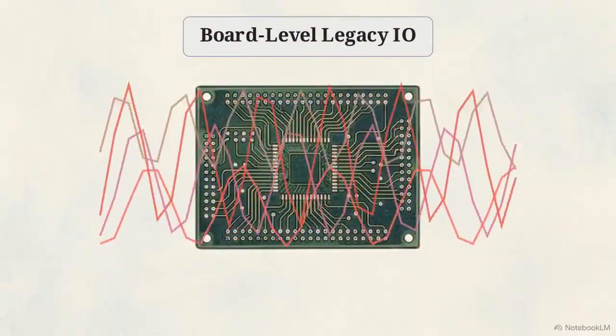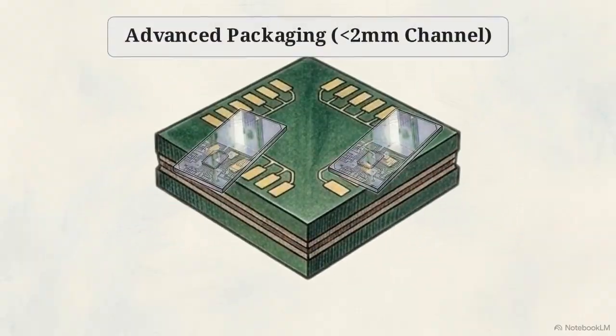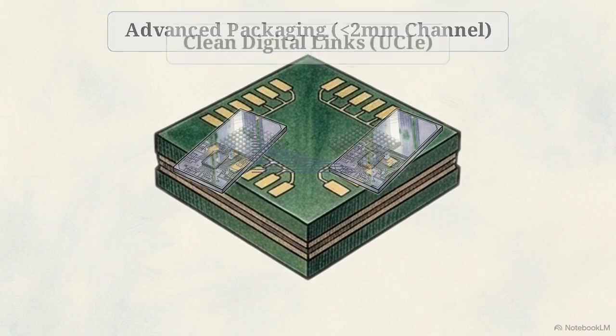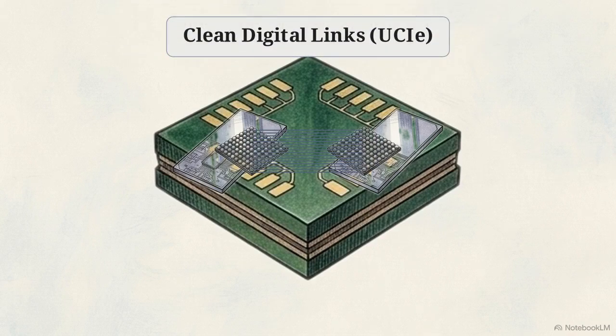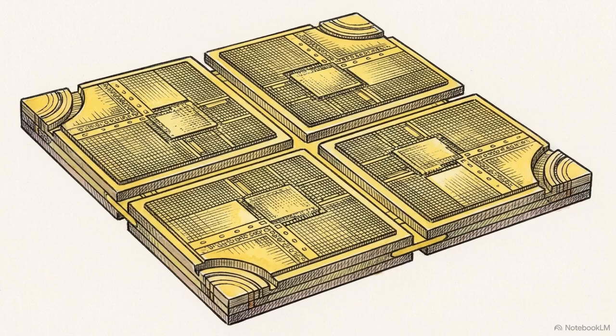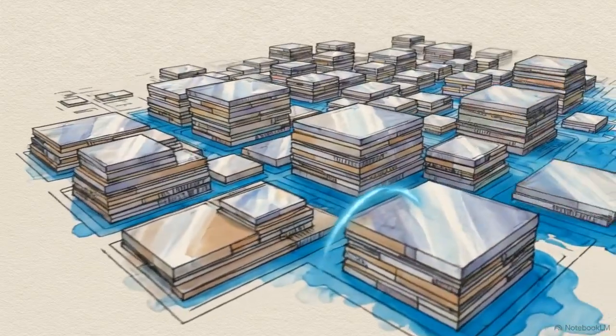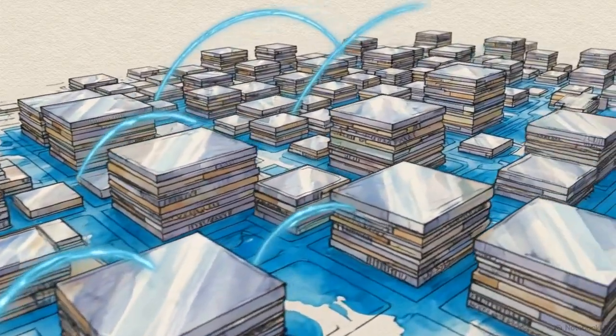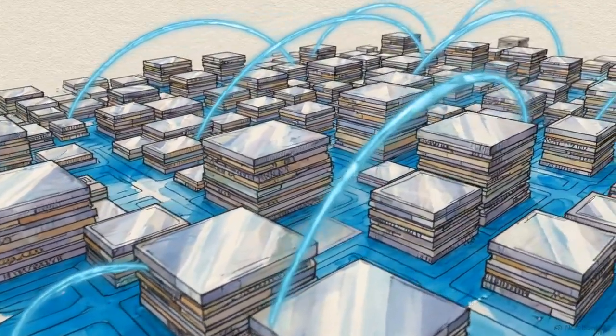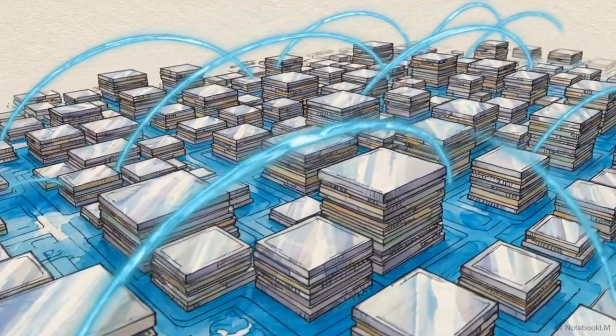By utilizing the specific physics of advanced packaging, hardware architects have engineered an interconnect that strips away the analog overhead of legacy I/O. A disaggregated multi-chip system can now behave, electrically and logically, exactly like a single monolithic die, allowing hardware architects to seamlessly scale compute density far beyond the rigid physical constraints of the reticle limit.